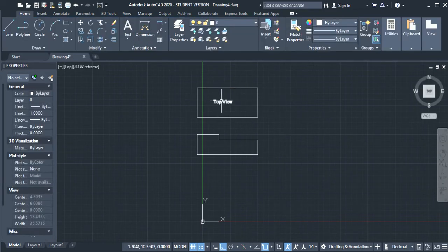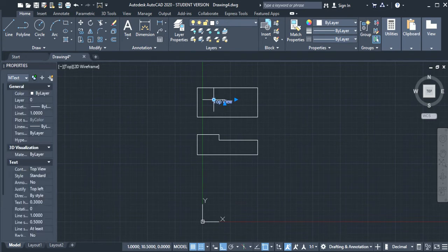It is, however, not very centered, so I'm going to go ahead and grab it. This little button here moves it around. You'll notice, however, it's still very snappy. So it won't allow me to center it very nicely. I'm going to go back down here, turn off snap mode, and now I can move it fluidly. Oh, I'm actually restricted in the ortho mode, so I'll go ahead and turn this one off as well. Now you'll see I can move it anywhere I want. So I'll move it roughly eyeball center.